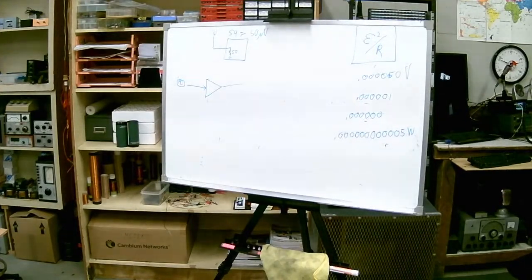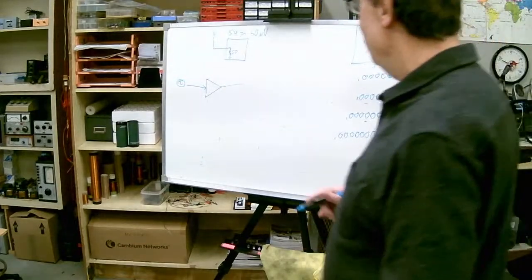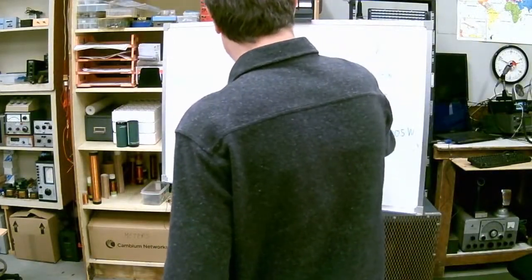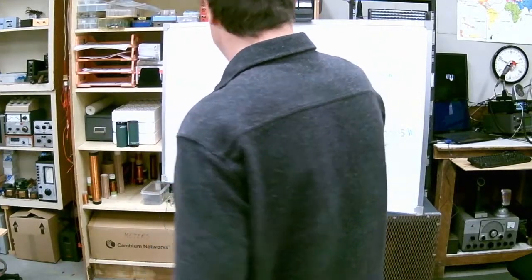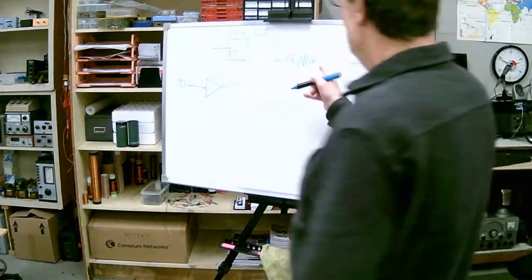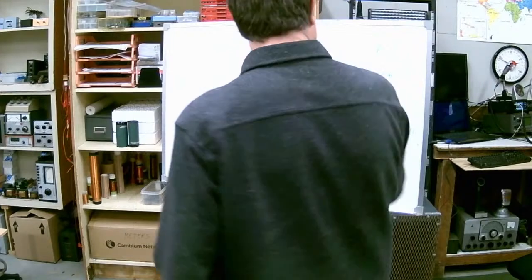On a typical earphone like that, they found a good, strong, not deafening, but comfortable listening level occurred when it was fed with minus 13 dBm, decibels relative to a milliwatt. A milliwatt is a thousandth of a watt, so it comes out to be a 20,000th of a watt.